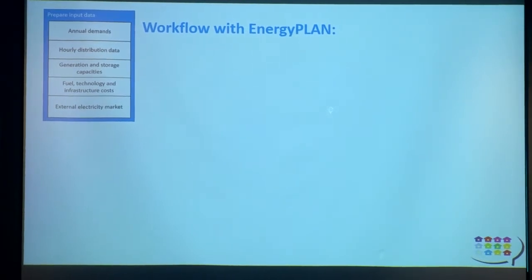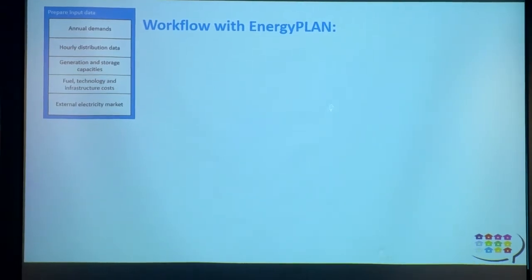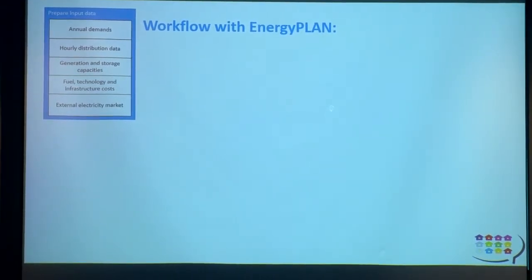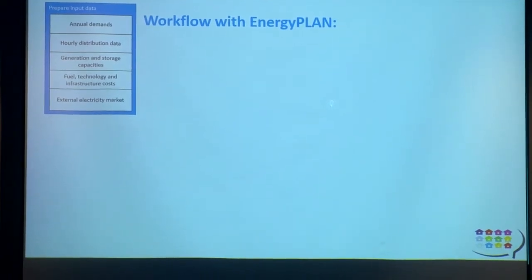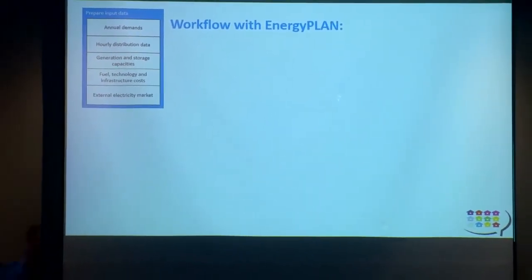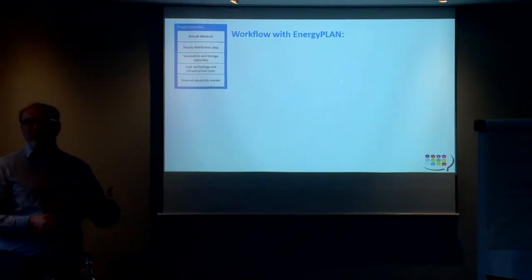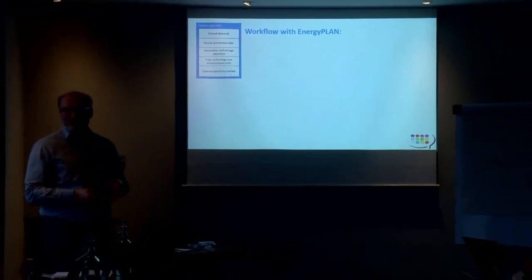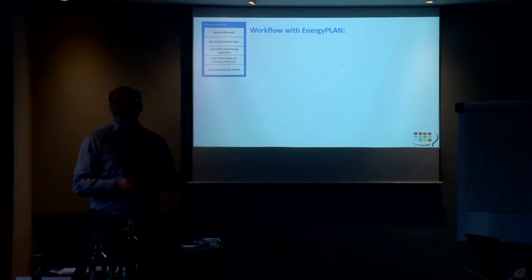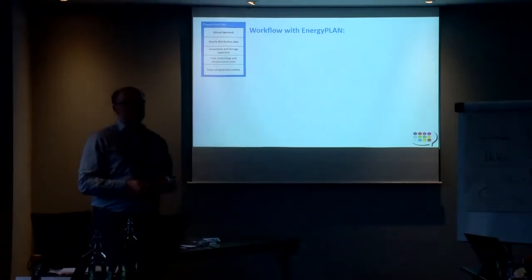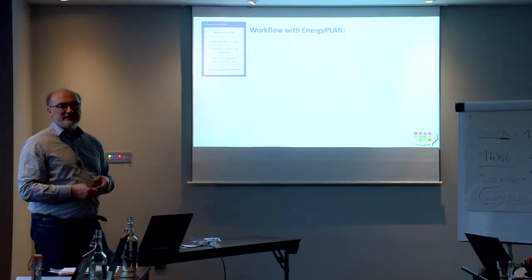But the assumptions in most cases, of course, can be justified by using standard rules, like, as we discussed, the kilowatt hours per square meter per year, for example, can be assumed. If most of the buildings, for example, when we talk about building heating demand, in your village are older than 50 years and have never been renovated, then we can assume they might use 200 to 250 kilowatt hours per square meter per year. Or if there are new commercial buildings, we have to apply the building standards. This is what we know.